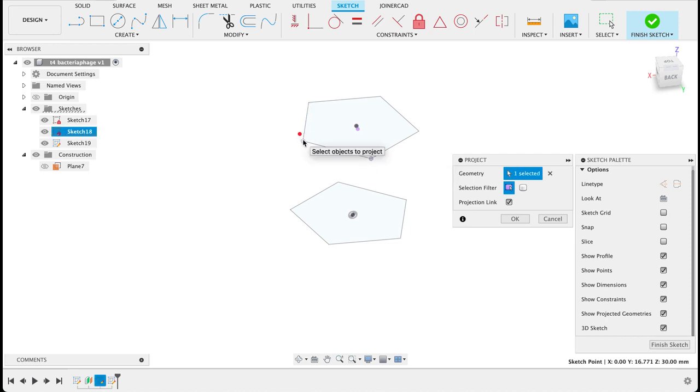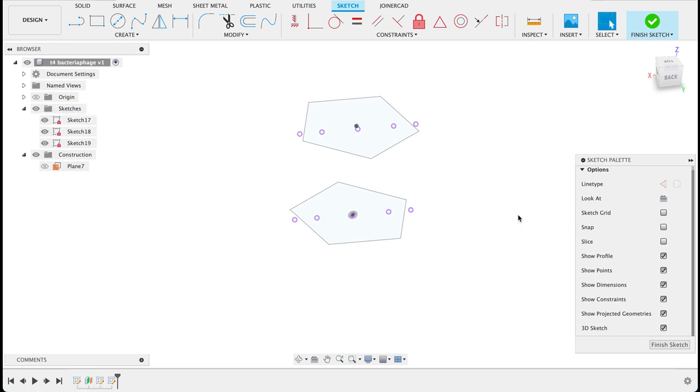Not quite giving me what I want, but now when you're drawing these lines, make sure you don't click on the little purple projections, because those are just where it's projected on that vertical plane that we're supposed to be drawing on. You see they're all in a line there. So we're going to make sure that we ignore the projected points, but just go to the points we can snap to.